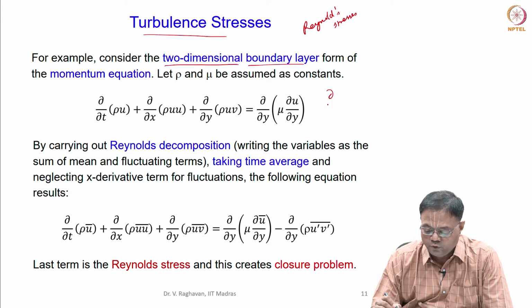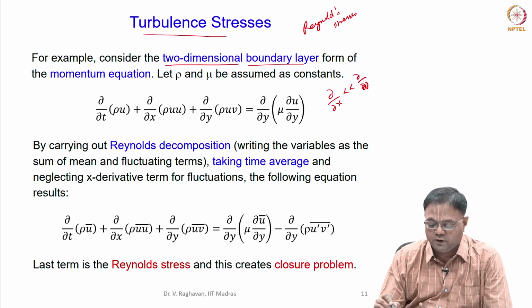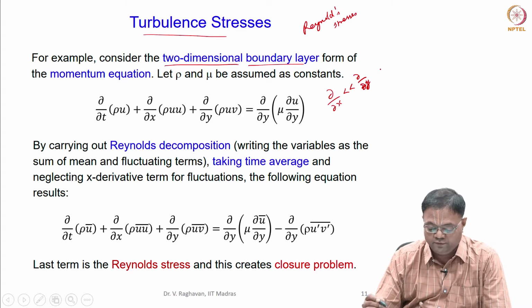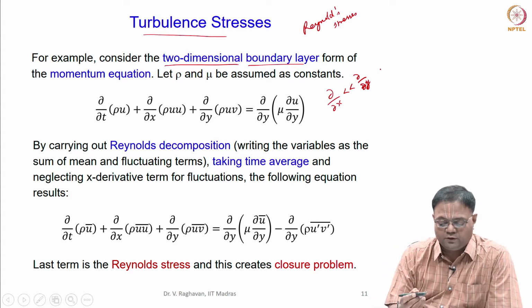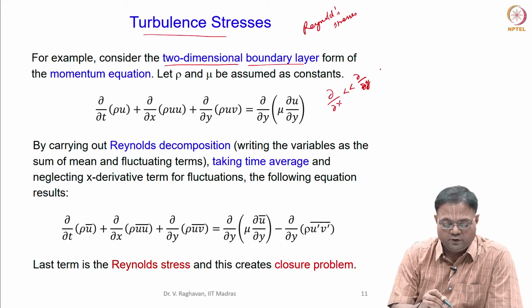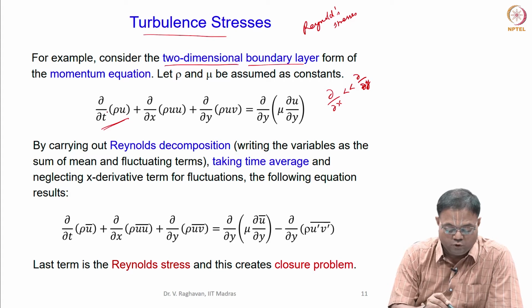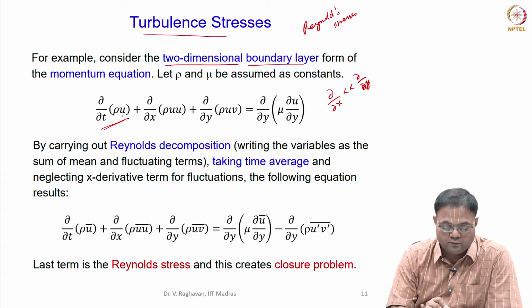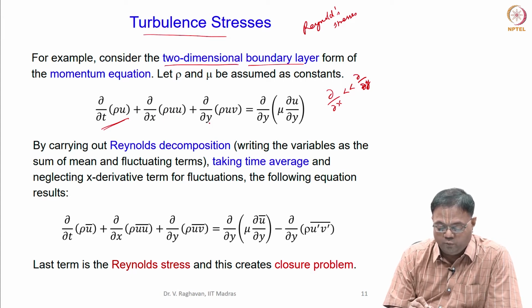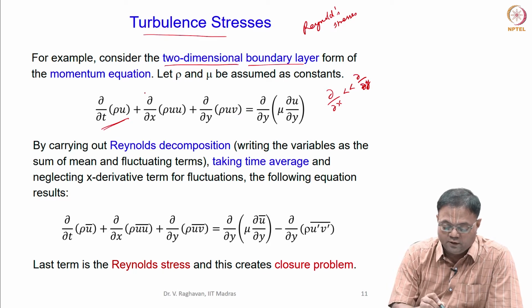Here you can see that the derivative in the x direction is not as prominent as the derivative in the y direction. So, the diffusion term basically does not have the x derivative, and since the turbulence is time dependent, we have included a time dependent term also here. So, dou by dou t of rho u, the x momentum equation, equals the convective term, dou by dou x of rho u and dou by dou y of rho u v, and this is written in conservative form.